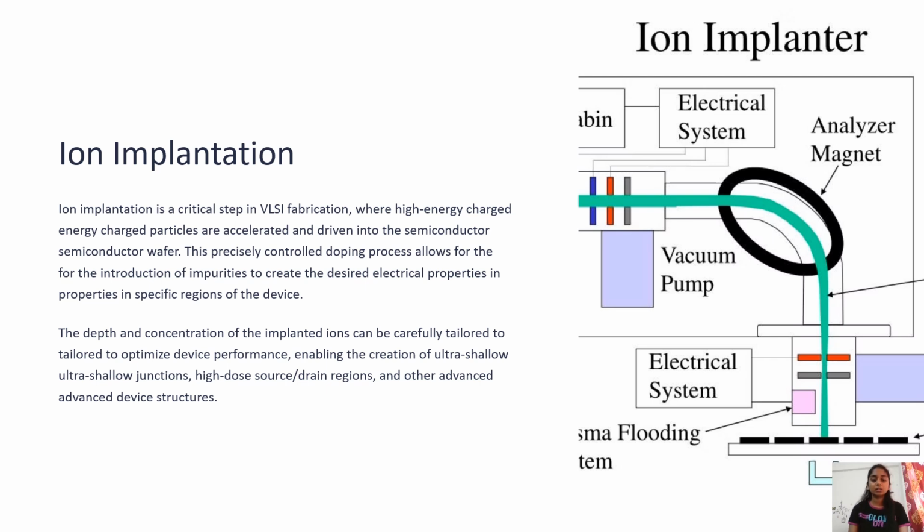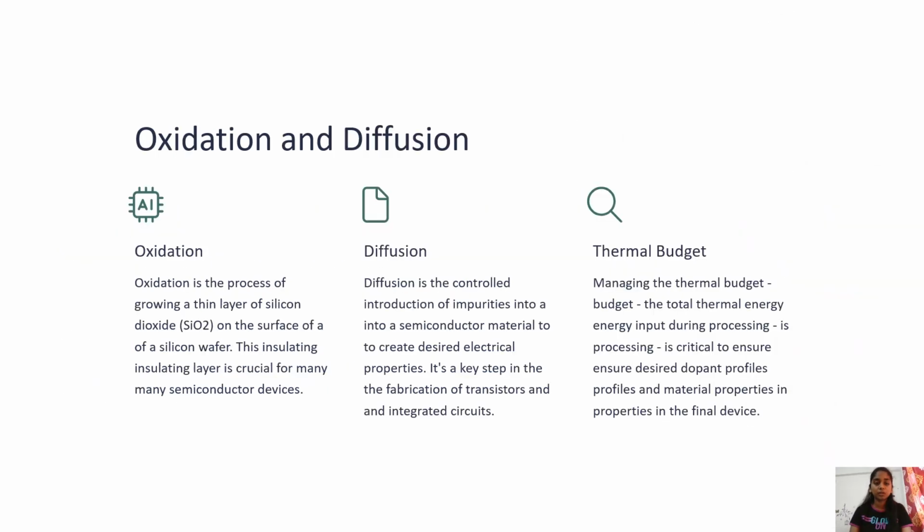The depth and the concentration of the implanted ions can be carefully tailored to optimize device performance, enabling the creation of ultra-shallow junctions, high-dose source and drain regions, and other advanced device structures.